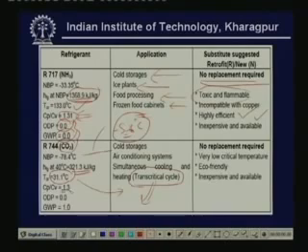Other important properties are it has a low ODP, and it also has it has non-zero ODP. Okay, I am sorry, and it has very low GWP. And its major applications are in cold storages, in air conditioning systems, in simultaneous cooling and heating. If you are using a transcritical cycle, you do not require any replacement. And major disadvantage is low critical temperature and high operating pressures. I did not mention this, but its operating pressures are very high, and it is eco-friendly, and it is inexpensive and easily available.